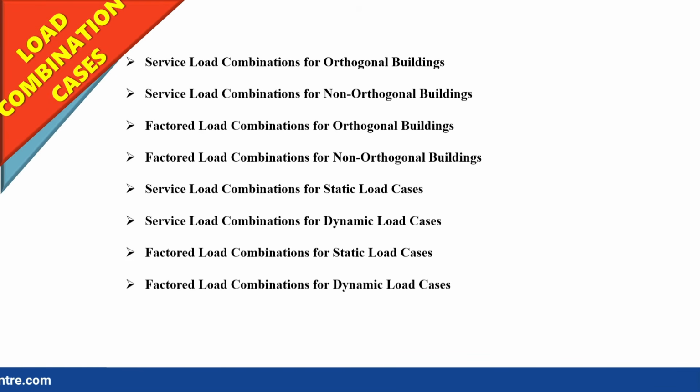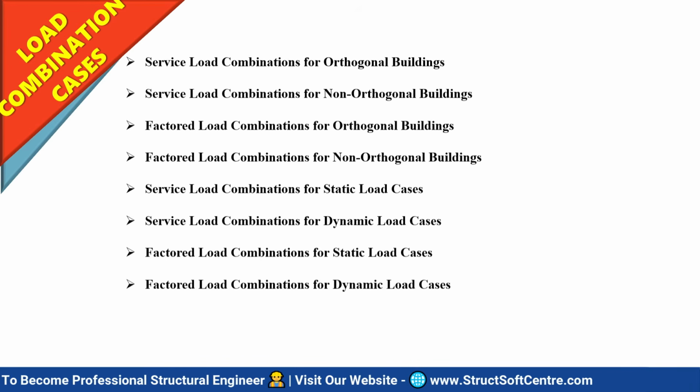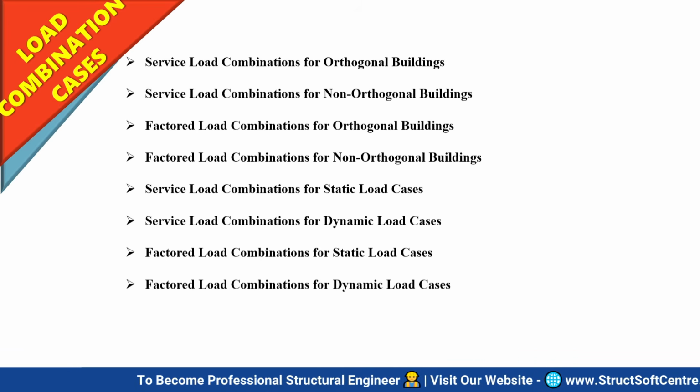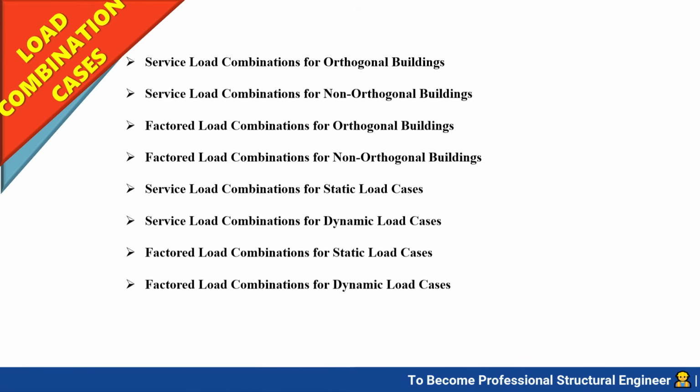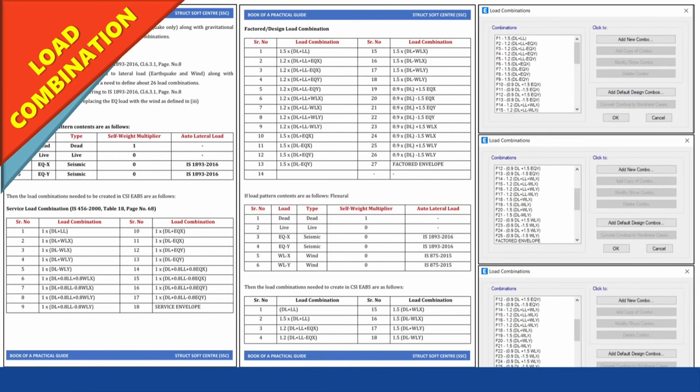You define the service load combination for orthogonal and non-orthogonal structures, the factored load combination for orthogonal and non-orthogonal structures, the service load combination for static and dynamic load cases, and the factored load combination for static and dynamic load cases. So how all these load combinations need to be defined in the Etabs software, we are going to learn in detail.